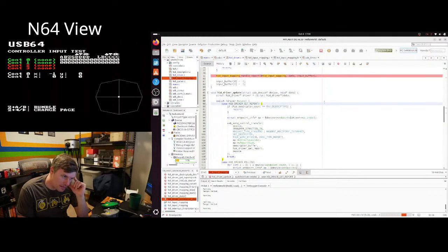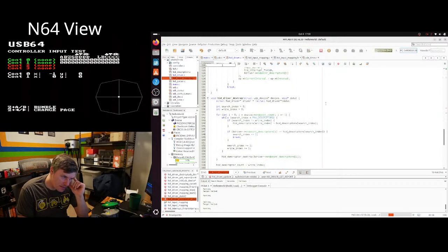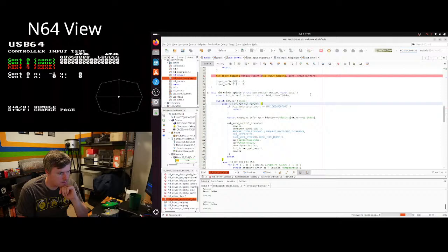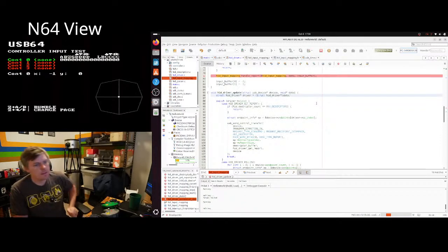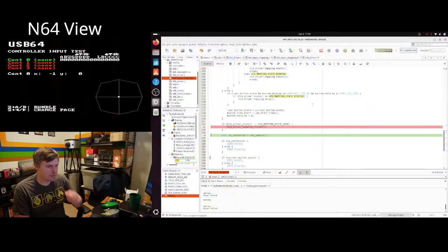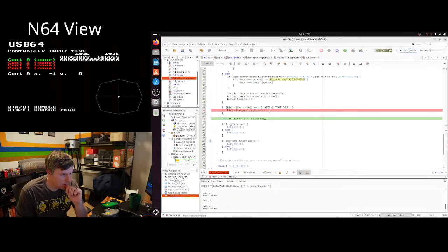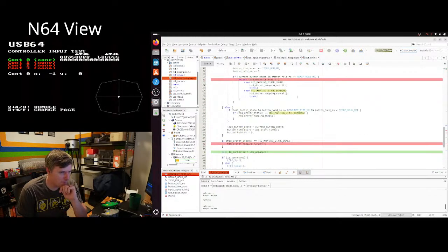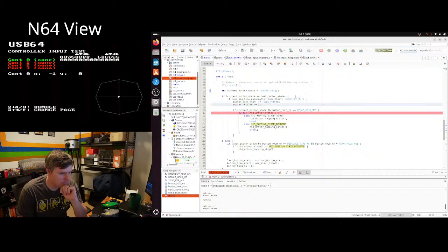Okay, I need to maybe see what the current state of the driver is. There might not be a driver loaded yet. It may have rejected the device. One reason it could reject the device is that I want to limit it to only devices that draw under 100 milliamps. Or for whatever reason it failed to parse the report descriptor because I have a bug in my parser, then that could have failed.